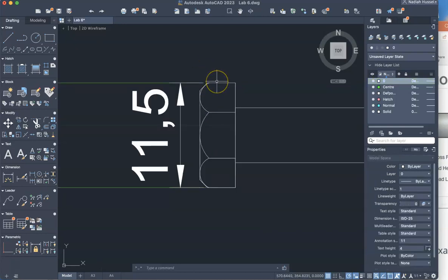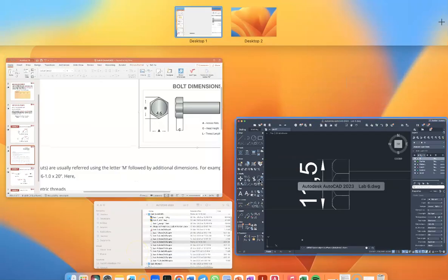I'm going to make an offset and try to align the arc to the offset. So my distance would be 0.1 maybe. And I'm going to select this object and try to offset. So that's kind of too small. 0.2. Okay, 0.2. So distance 0.2. Select object. Okay, I think 0.2 is okay. Let's see if that looks sufficient.